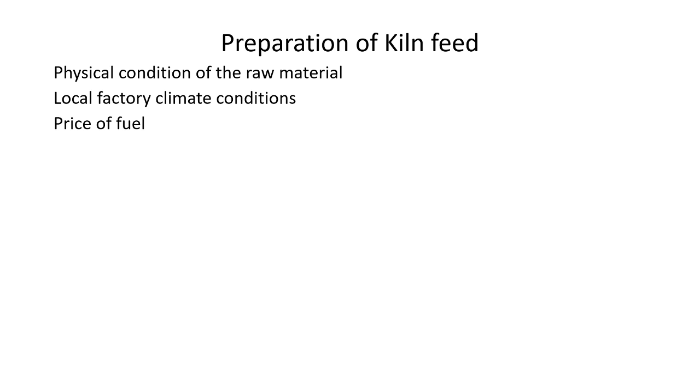It is selected based on the physical condition of the raw material, the local factory climate condition and the price of fuel. If the raw material is soft and the climate is fairly moist, then the wet process is used. Otherwise, the dry process is the most favorable.